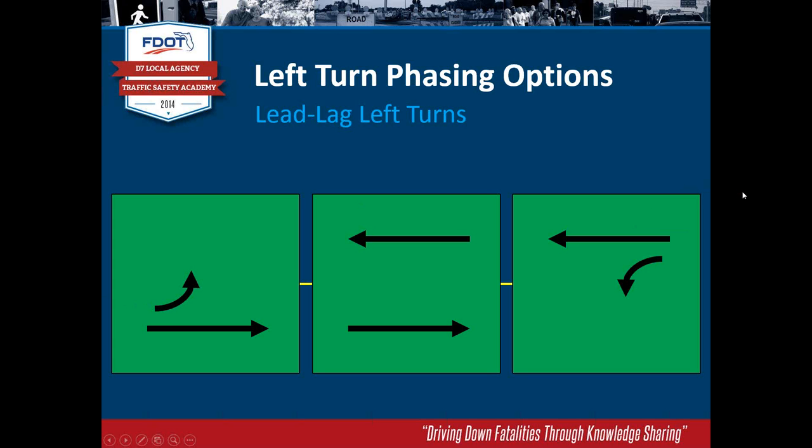And then the other direction arrives because it's further away or its green time is offset a little bit differently. It arrives a little bit later in the cycle, and so you want to, again, pass, in this case, the left turns, make sure they can pass through the intersection without stopping. And so, again, this kind of thing can be implemented. Typically, it's primarily for progression.